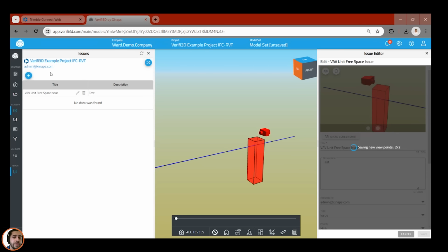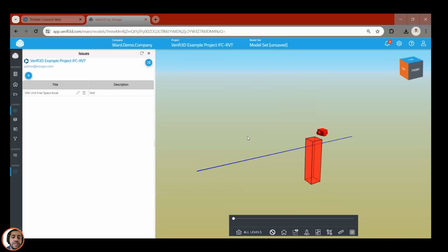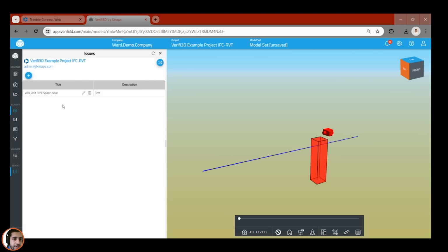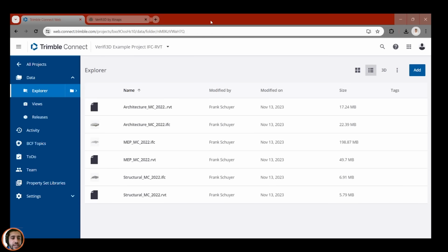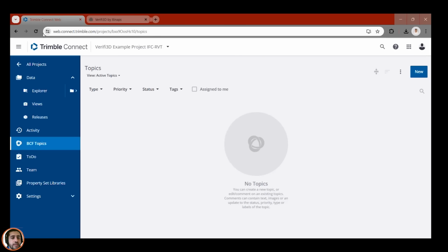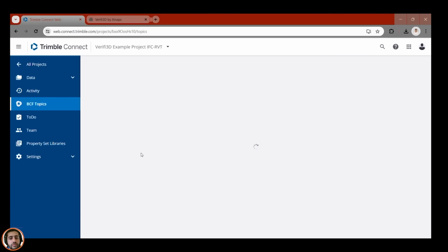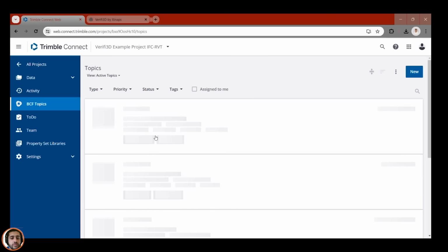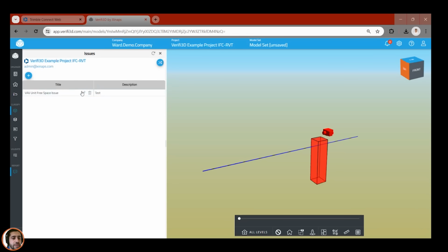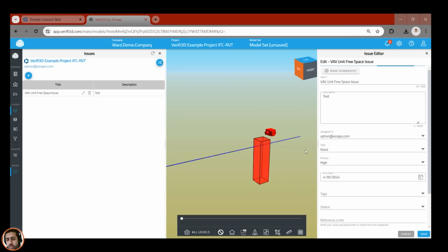And now the issue is being real-time synced to BCF topics on Trimble Connect. Now you can see it here on Verified. I'll just go to my Trimble Connect account. I go to BCF topics, and then I just need to refresh. Perhaps I need another entry from here.